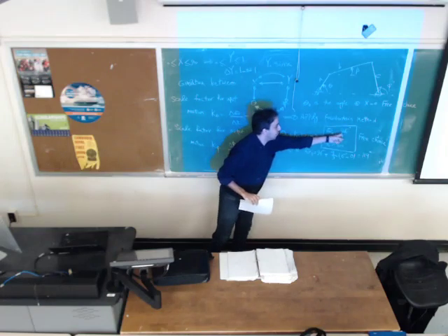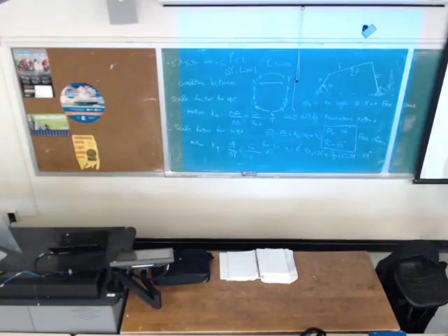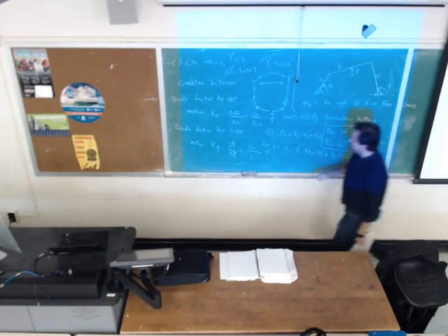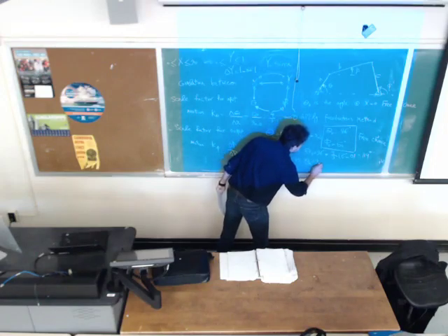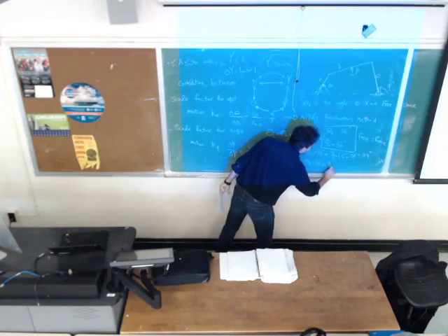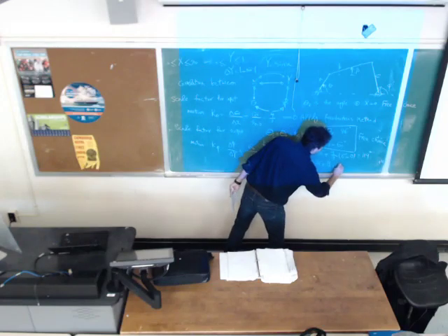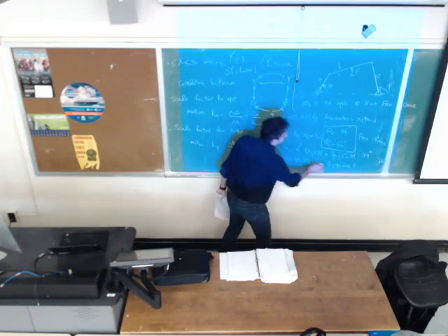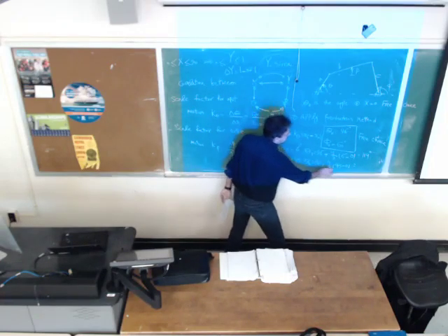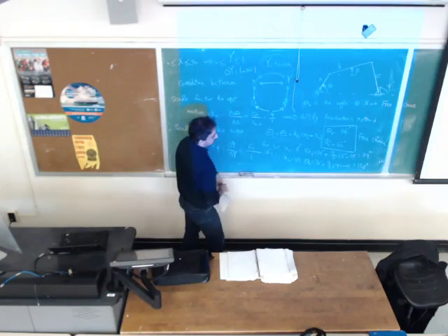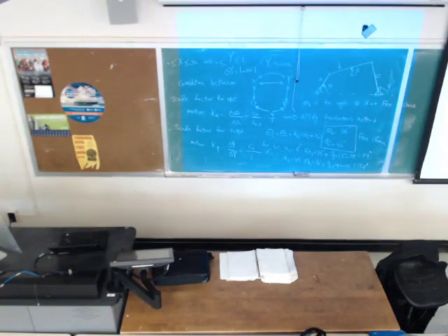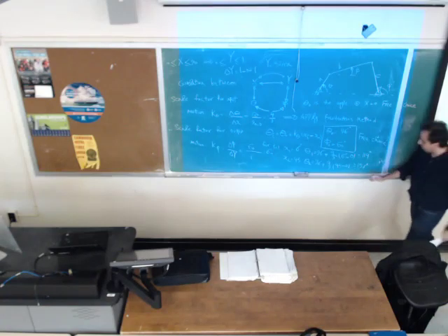So by picking this free choice for theta naught, it tells me when this guy is moving from 0 to 6 degrees, x1 is 6 degrees, the angle of the input link is going to be 114. It's moving from 96 to 140. Second precision point, it's 45. Theta 2 is 96 plus k theta, 4 over 10, x2 is 45, x naught is 0. 45 divided by 3, 15, times 4, 60, plus 96, 156. So theta 2, the angle of this input link at the second precision point, should be 156 degrees.